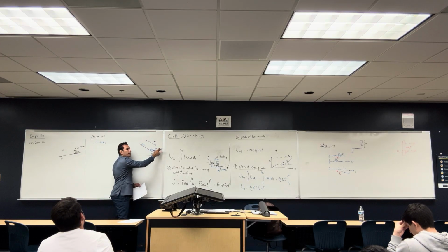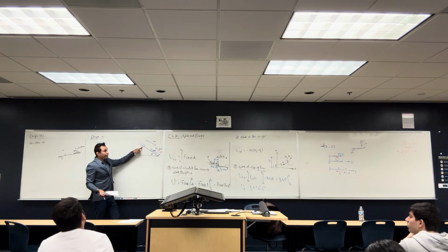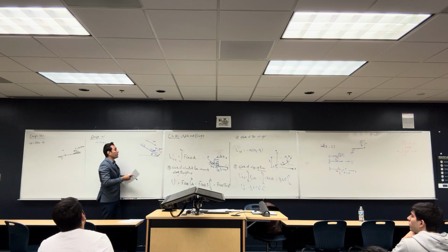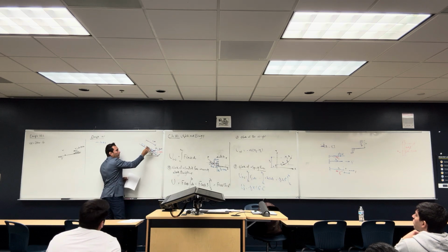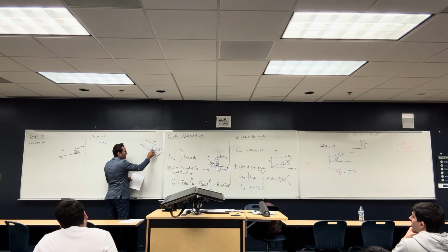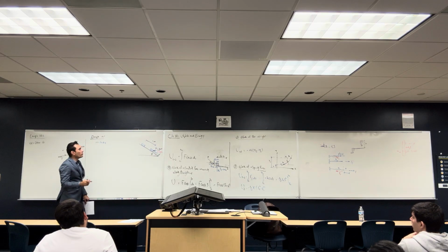How about B? Is B doing work or not, given that it's moving up? The horizontal component of B, the component in the direction of the movement, is the one that does work. It's the same thing: if you multiply B by cosine theta and multiply it by 2 meters, it gives you the same as taking the horizontal component of the 2 meters and multiplying it by the 400. Both give the same solution. What else? So it's B and weight.